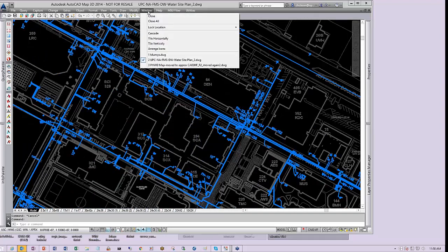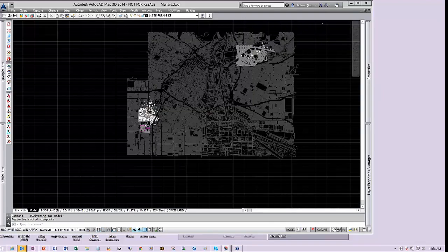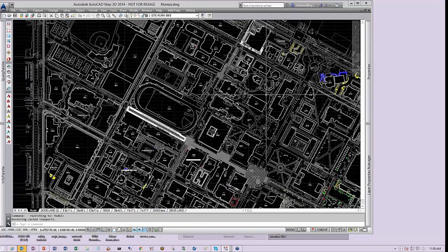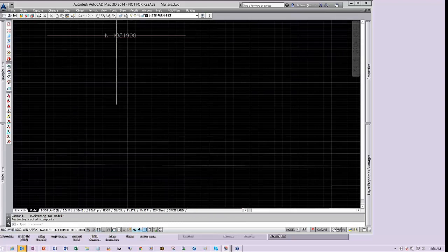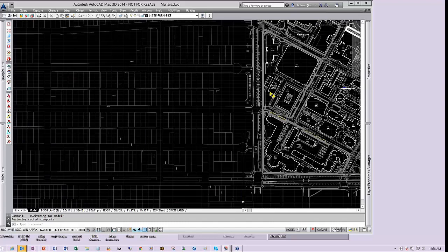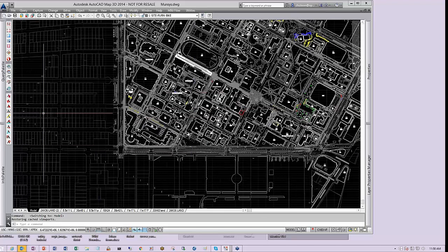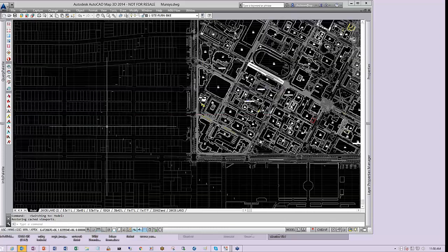And so I'm going to go to this data set. So if we look at this, in here, this has been located so it's geographically correct. And we've done that by looking at, if you look carefully, these are actually the state planes that were on the original CAD plans. So they had a grid and their map was there, and so they've got all the map sheets laid out according to that grid. And so we could actually use that, even that this position has a known coordinate, its position on a piece of paper at 0, 0.